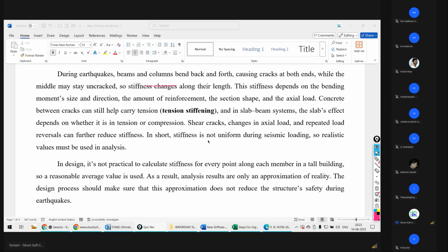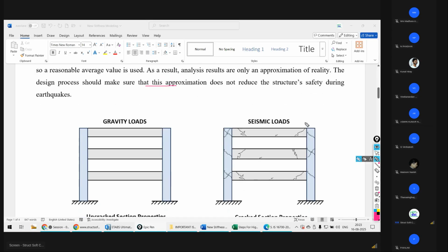At that time, high stress zones are going to be formed, and those high stress zones will be your beam and column connection at every one of the points, beam and shear wall connection at every one of the points. This is what we are expecting, or this is what has been seen most of the time, but it is unpredictable. The high stresses may also be formed at this point, because reversal movement will be there, reversal action will be there.